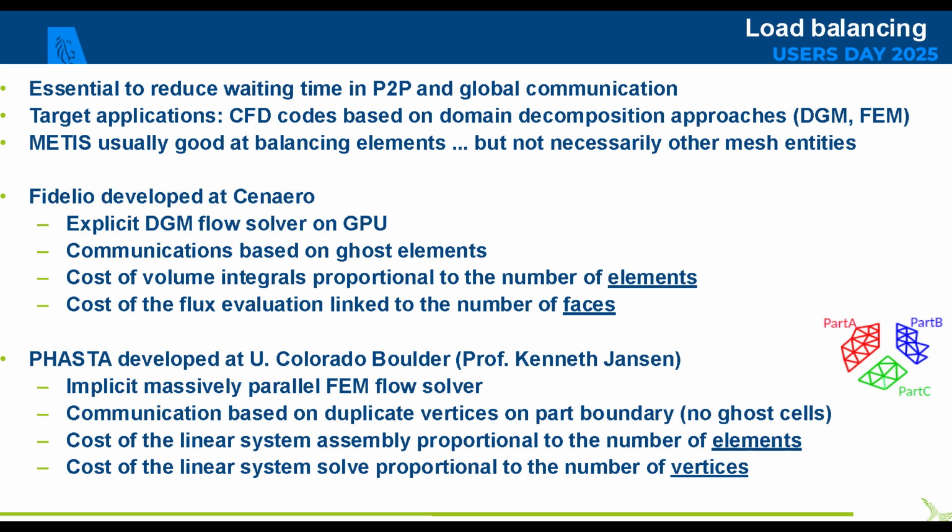The first one is a code that is being developed at Cenaero called Fidelio. It's an explicit discontinuous Galerkin method, designed to solve for flow simulation on GPUs. This particular code is based on ghost elements for the mesh partitions, and that means that the cost of volume integrals will be proportional to the number of elements, so usually easy to balance,